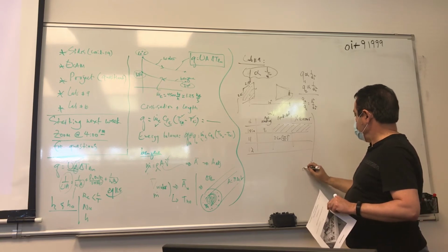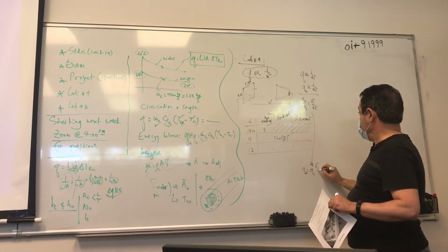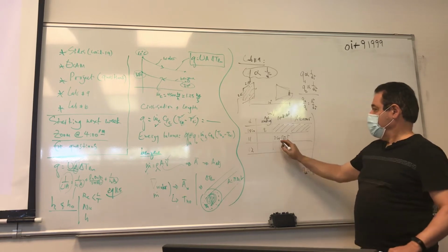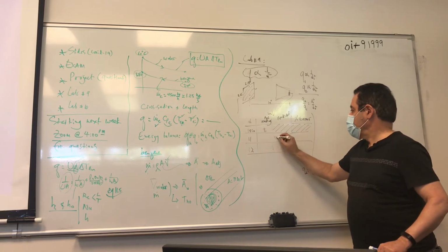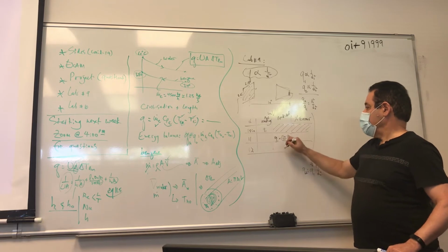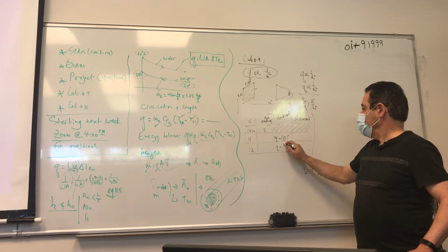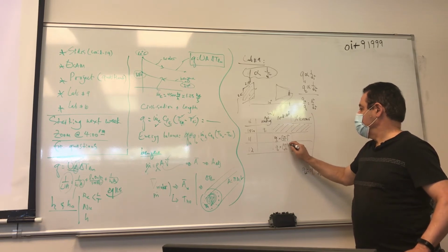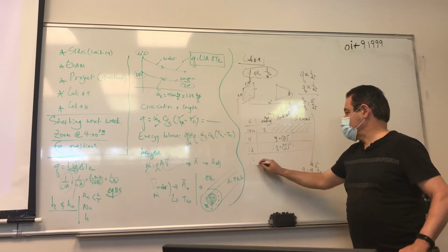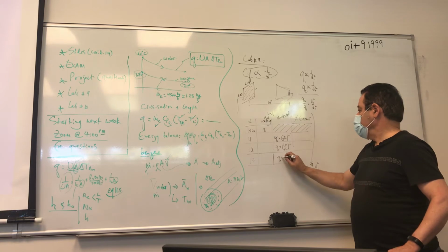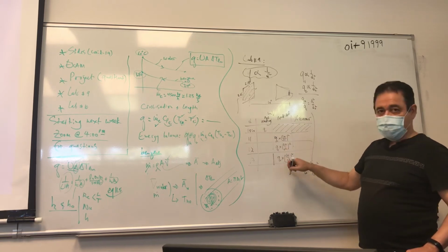This means that Q2 is always going to be equal to Q1 times D1 squared divided by D2 squared. So here it's going to be whatever value we read as Q1, times 10. How about here? It's going to be Q1 times 10 over 12 squared, and then 13, and so forth: Q1 times 10 over 13 squared. So this is what we're going to be doing in the lab.